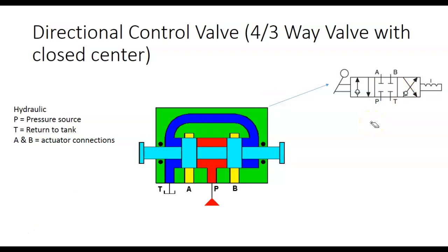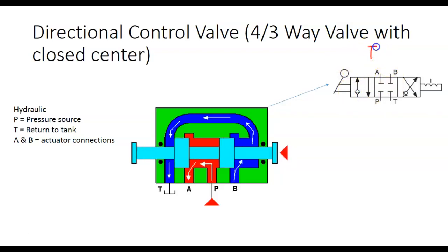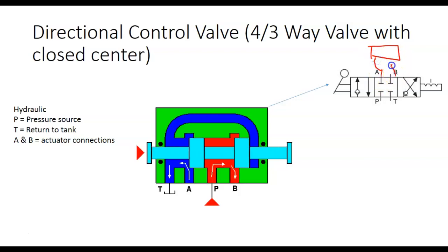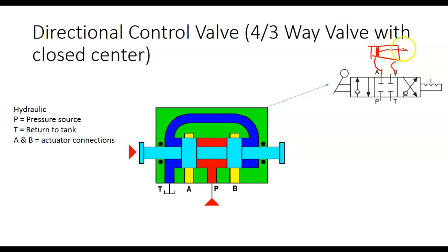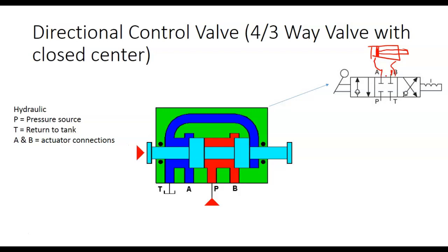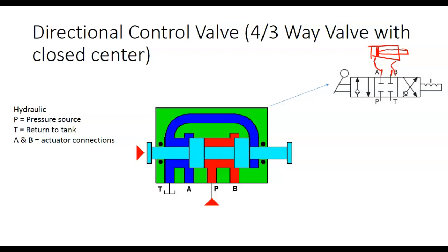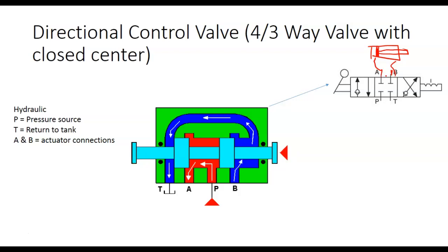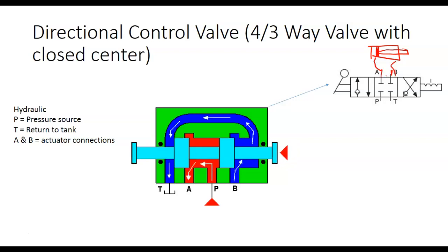So what that means is, and don't pay any attention to the check valve, I got my actuator up here. So let's say we got a double acting cylinder. This goes here and this goes here. Now this will work real well on hydraulics. It doesn't work that well on pneumatics. And when I put that in the center position, that actuator will not move. Because why? There's no place for the fluid to go. So these closed centers, this would be what we'd use in hydraulics if I wanted to stop the actuator somewhere in the center. I didn't want it to go its full stroke.